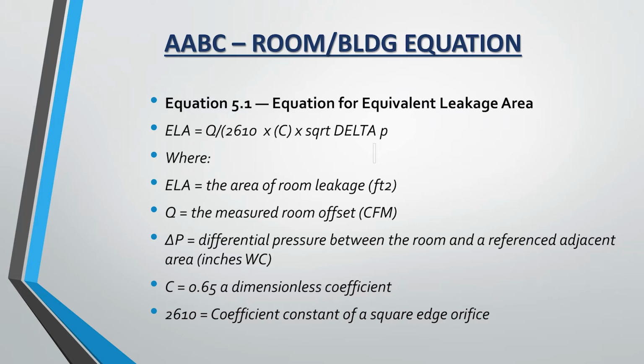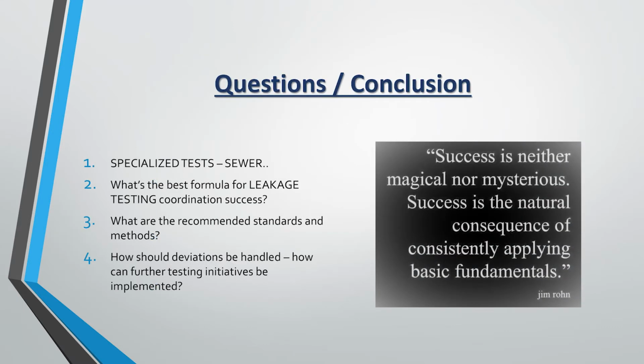I am no expert and I have very limited exposure to building or room testing, but I do know that, in the couple I've been to, there are many different opportunities to have errors here, many. Does anybody care to offer an instance of a room or building pressurization case study? One of the issues that we discovered is you've got to be very meticulous in doing your area takeoffs, because a couple thousand square feet can impact your results.